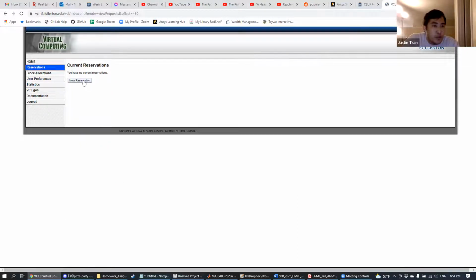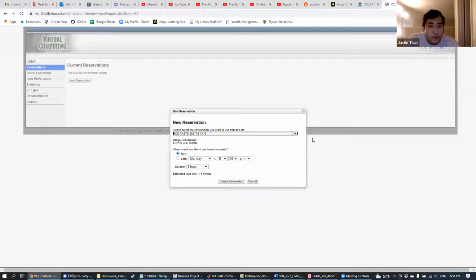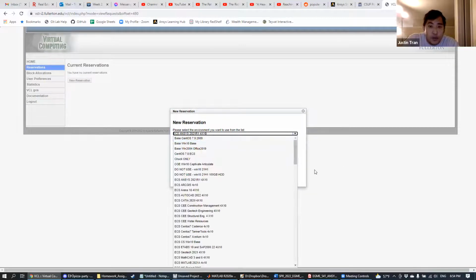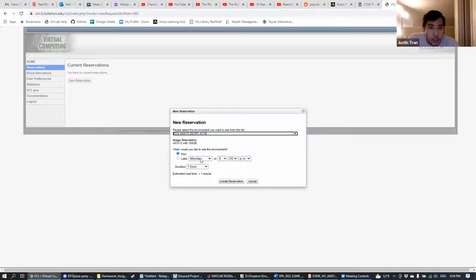You click on reservations, you click new reservation, and you need to choose Ansys from this list. They have a lot of different images available, and what you want is ECS Ansys. They might have 2022 already, actually. Let me see. Actually, they only have 2021. So you do ECS Ansys 2021. You said you want it now. And then you can specify the amount of time that you want. If you want it to last the whole lecture, you can do 2 hours, or most times I do 4 hours. Then you click create reservation, and you can just follow the directions on screen.